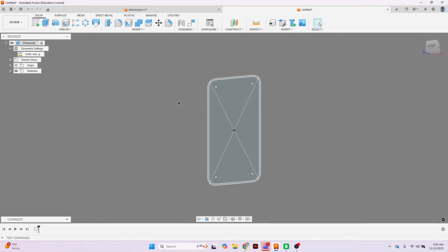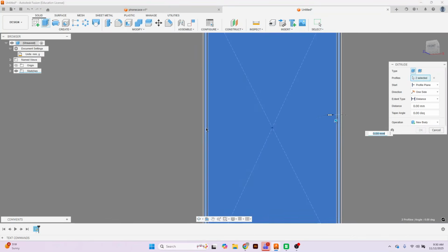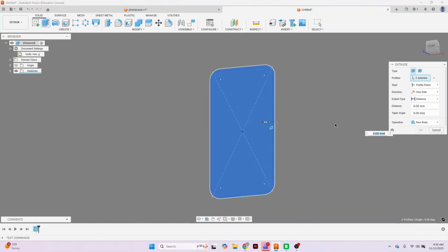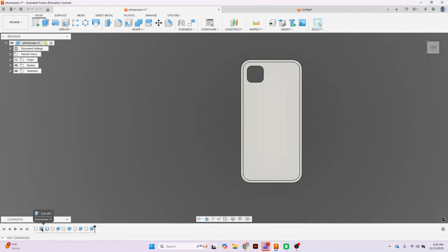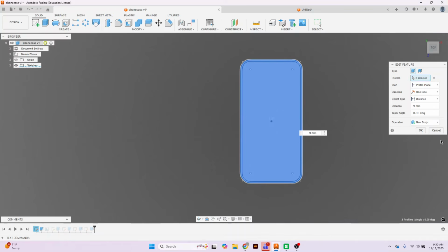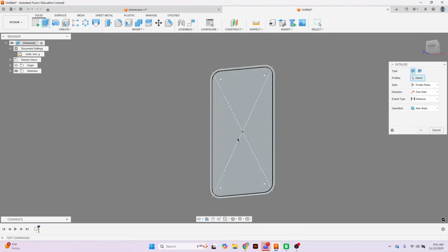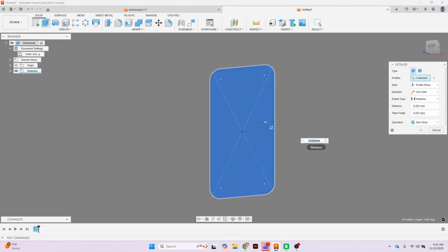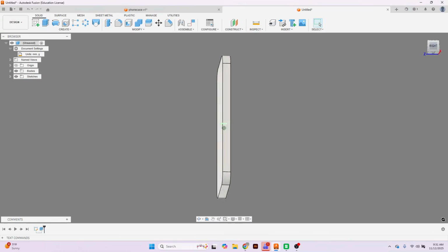Once we got that going, we can finish sketch and then extrude. Make sure you extrude both the main part and the offset part. You know what? I don't remember the dimension. Let me check that. Finish sketch here. 9 millimeters. So extrude 9 millimeters.